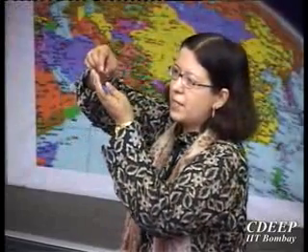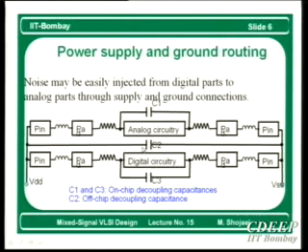So what I do is I have this signal line, and I put a ground here. So it is like that. Instead of around the wire, I have kept it on top of the wire, or I keep it on the same level adjacent to the wire. So this is shielding. But here, this capacitance, at high frequency, makes a short circuit, and it is able to draw all switching currents without showing any impedance.